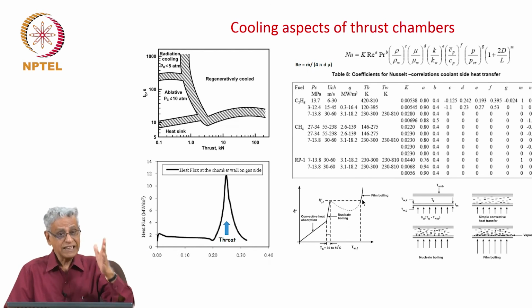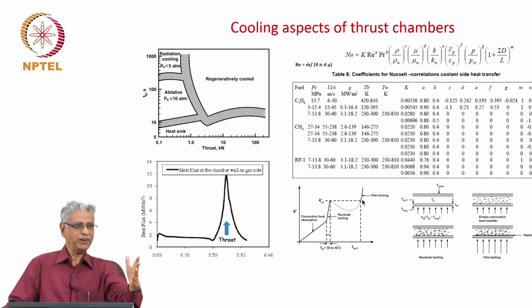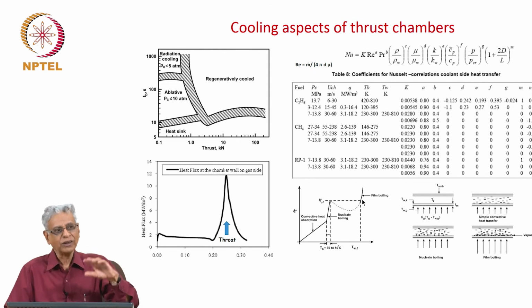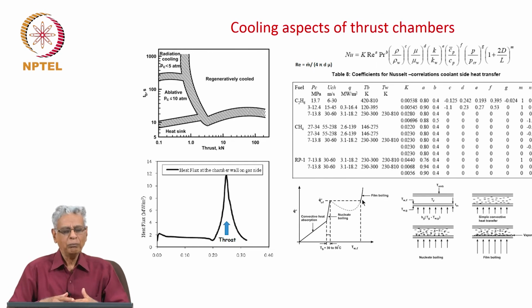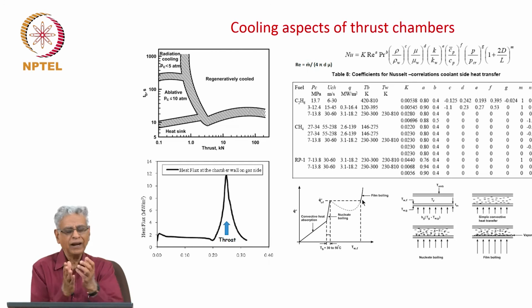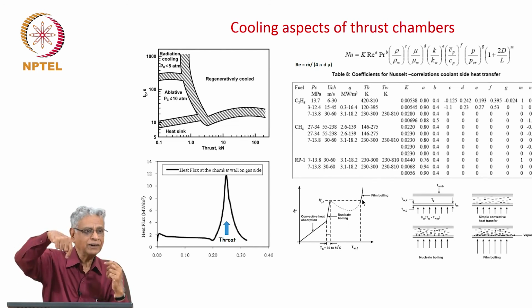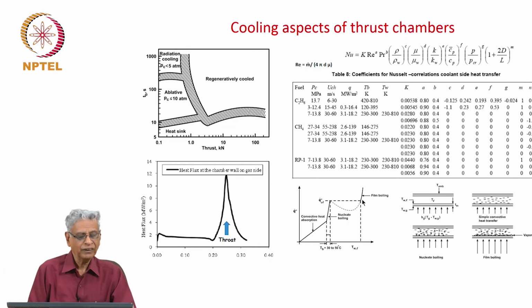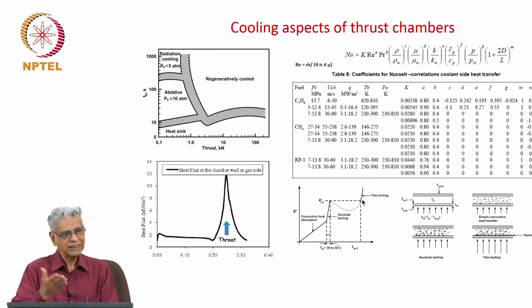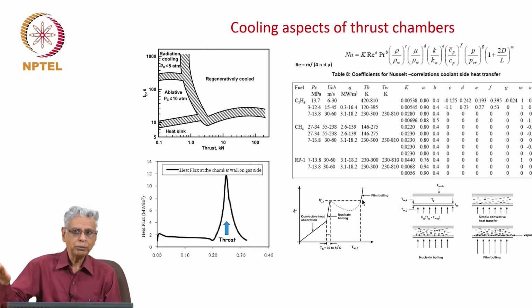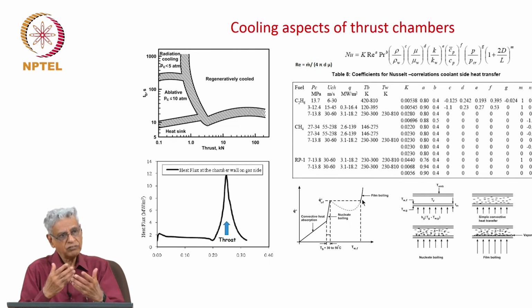So, that is why this design is a very critical feature, and to ensure that this does not happen in regenerative cooling systems, they use many strategies. They introduce the liquid into one place, take it downstream, take it upstream, and introduce additional liquids somewhere. In the case of the engine which is being built in ISRO, many of these strategies are also deployed. That is because the Russian design on which this is based has very similar features.